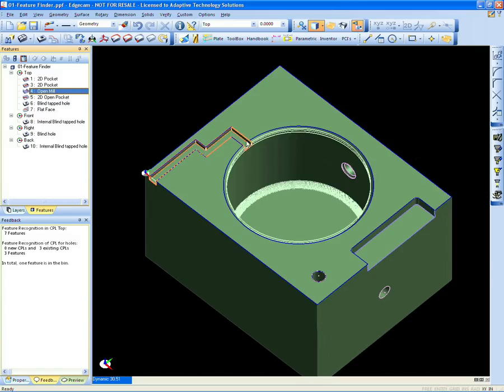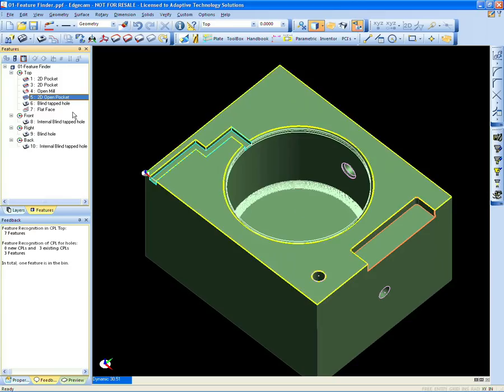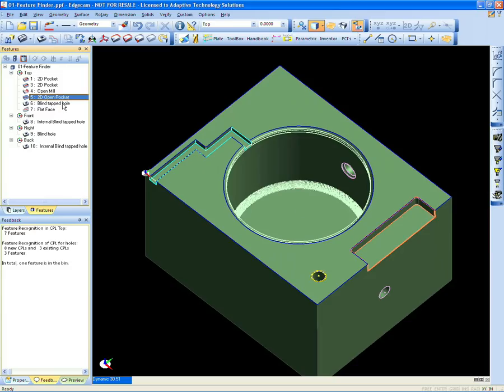So here again are some pockets. You see the open mill pocket where it looks at the floor of the feature and builds up the walls from that. There's a 2D open pocket. This can be nice as well. So if you rough this out, there's the option in the roughing cycle that prevents a rollover condition, so the tool will move straight in and straight out.